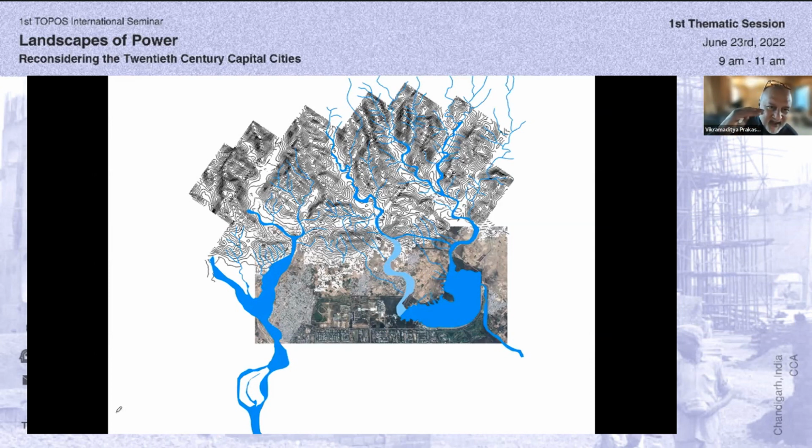So it's the very first thing that is going to be eroded. Our conclusion is that the siltation of this lake that we are looking at is a foregone thing. There is no way to stop it, which is also what we have found in the big hydroelectric projects located in the foothills of the Himalayas. They silt up.